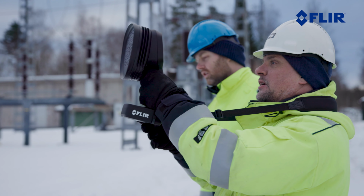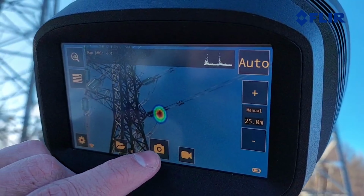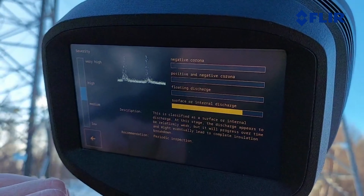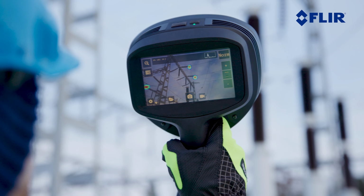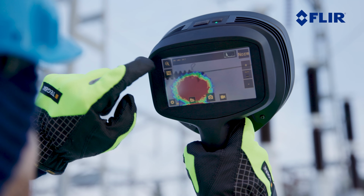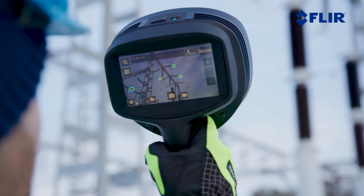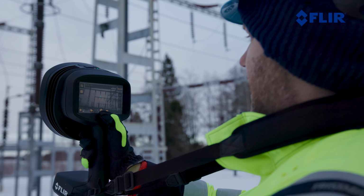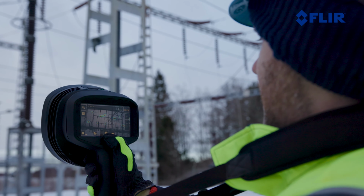Only about 15% of all partial discharges that are detected indicate an impending catastrophic failure. The SI2's on-device severity assessment instantly highlights the PDs that demand your attention. You can adjust screen brightness and zoom in and out with the camera. You can use the multi-source mode to scan a large area quickly and take note of several sound sources, which you can then inspect more closely with single source mode. Note that when visualizing multiple sources, the camera will only analyze the strongest sound source indicated on the screen.